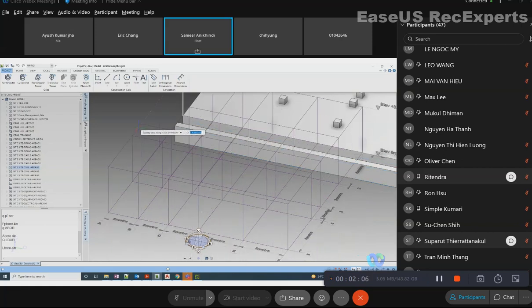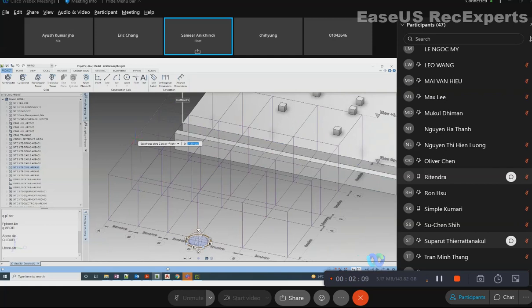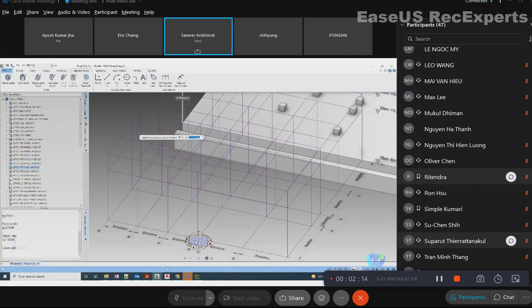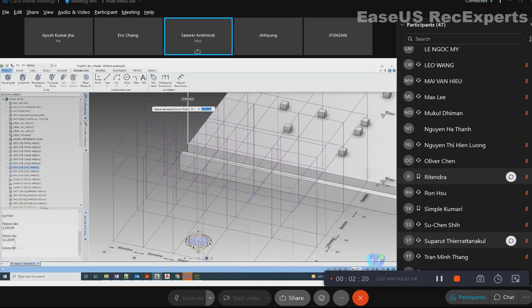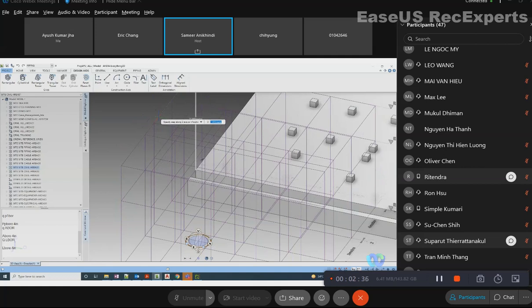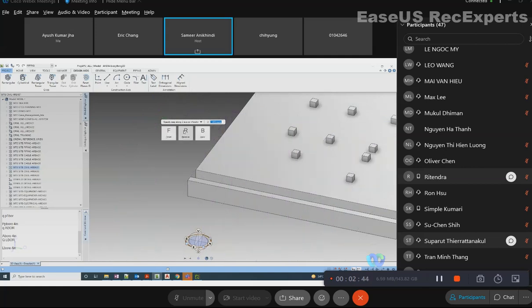Now in Z direction or elevation, remember one thing: when you specify distance, say 5 meter, the next distance you have to specify in absolute elevation. Right? You want 2 meter above 5 meter, you should specify 7 meter. Unlike X and Y direction, which take the relative distance with respect to the previous plane, in Z, by default, it takes absolute elevation, not the difference with respect to the previous Z plane. But you can press down key and make it relative.